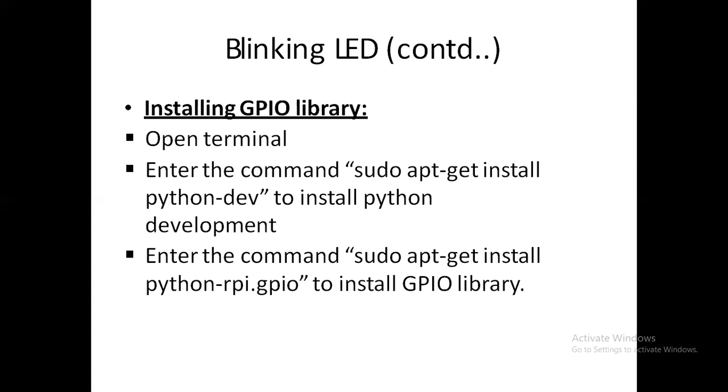We can use a ribbon wire in order to have a connection. It is already available with the Pi cam, and the blue side should be pointed towards the Ethernet port. This is one of the points to remember.